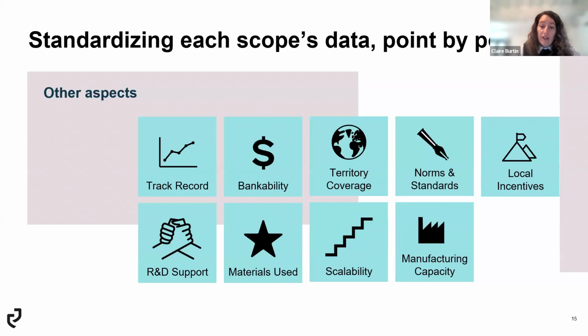For Chinese vendors, the calculation is done differently because the norm is different in China. They calculate using the electricity input instead of the hydrogen output, and by doing that, they are overestimating the efficiency of their systems. Not voluntarily, but that's the way the norm is compared to Western vendors. So there is an overestimation of efficiency by around 10%.